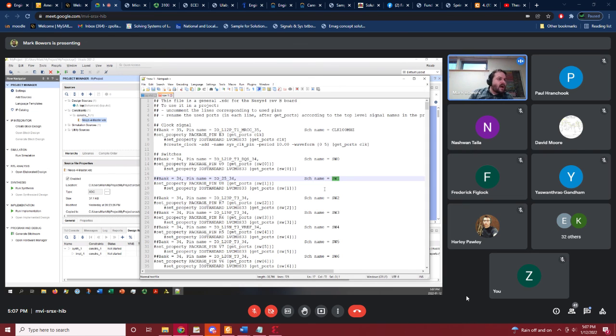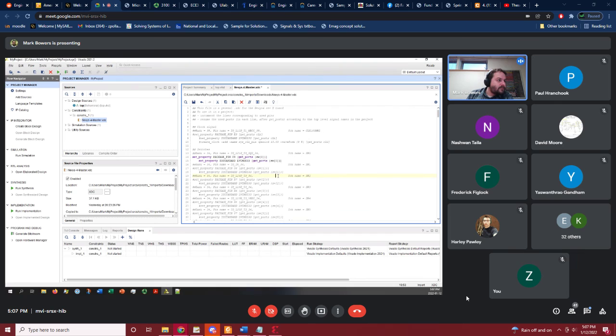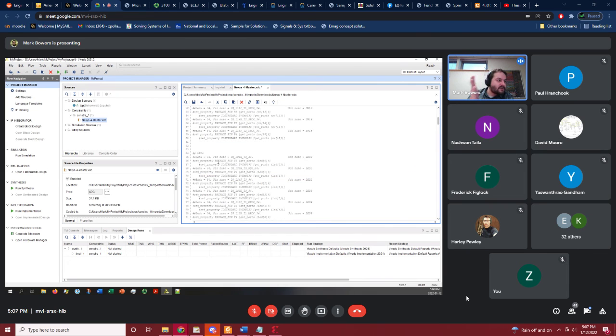The pins that we're going to use in our design, we actually have to go here and uncomment. When you do that, it will color them to show they've been uncommented. We're sort of enabling this pin on the FPGA. We're also going to use LED 0, so we uncomment that as well. Everybody see what I did there?